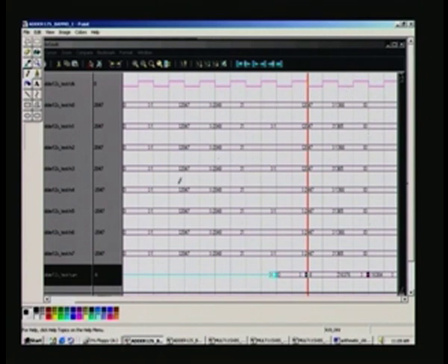And so I will zoom this here, and let us say we have already seen that there are 5 pipeline stages inside. So, naturally the result must manifest only after 5 clock cycles. Let us have a look whether it is so. The result starts here, you can see 0 here, this result. After zooming you will be seeing it clearly. Right now just be content with the waveform that you get here. So, 1 pulse here, 2, 3, 4, 5.